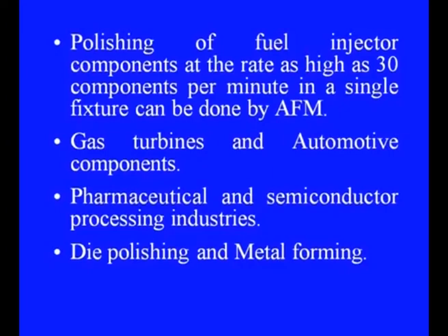Some other applications of abrasive flow machining are finishing of extrusion dies, nozzles of flame cutting torches, deburring of aircraft valve bodies and spools, removing recast layers after ECM or EDM or even in casting, then precise edge finishing of gears and deburring, then radius forming, then polishing of fuel injector components at a rate as high as 30 components per minute in a single fixture,